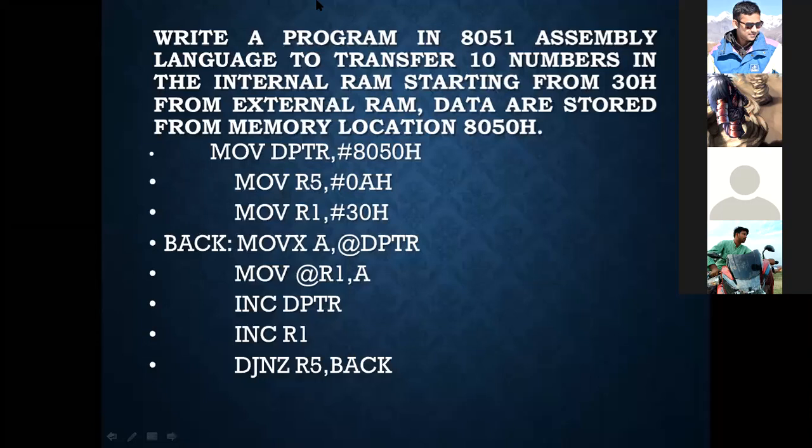Clear? I'm repeating once again. DJNZ R5, that means here decrement the content of R5. This is the counter. Clear or not? Am I audible to all of you? Yes, sir, clear. Okay. So decrement the content of this R5 and jump if not 0.